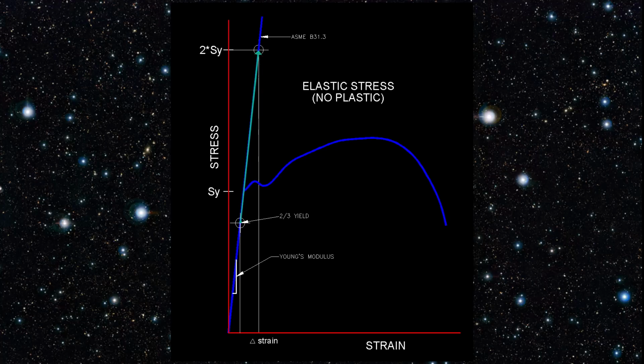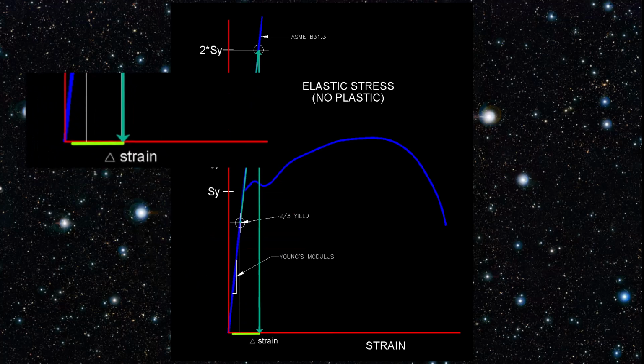One immediately thinks that because we are going to 2 times calculated yield, that the strain within the metal itself would be very significant. Now going down vertical, we can see how much strain was involved in the actual steel. Even though there was double the yield stress calculated, the actual strain in the steel did not increase very much at all. That's because it is self-limiting.